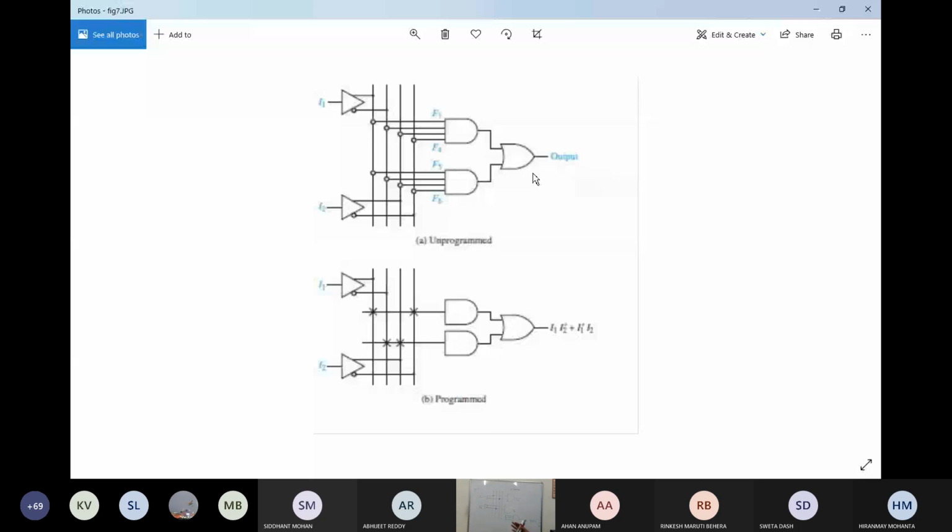The manufacturer will have a particular design. Since this is available, we will do the soldering. These are the tasks. That's all. This is how it is done. We have all possible availabilities and an array is there. Why is an array provided? We can in fact remove some of the gates and go for cost minimization. Everybody needs something different. That's why all the possibilities are provided to us, and depending upon the task, only those gates are soldered, electrically connected and then given. Is that clear? Because we have a lot of hardware available, because arrays are there with us. Is that correct?